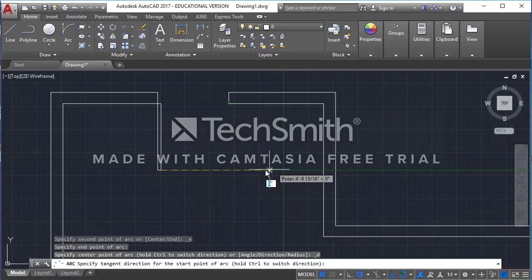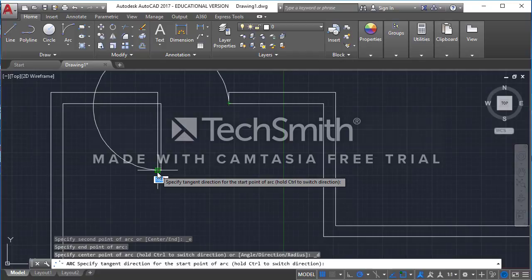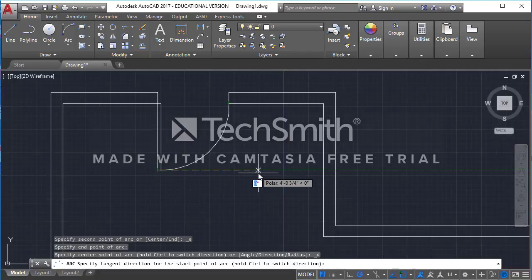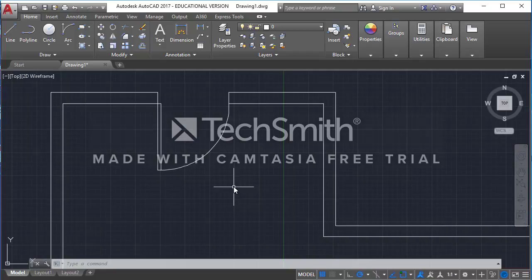Then from there, all you're going to do is specify a direction. Notice if I just move my cursor over to the right, it's going to create a perfect arc at a nice smooth tangent. If I move my cursor over to the other side, it starts to create a perfect circle. But I'm going to move my cursor over to the right to where it gives me a nice perfect arc.